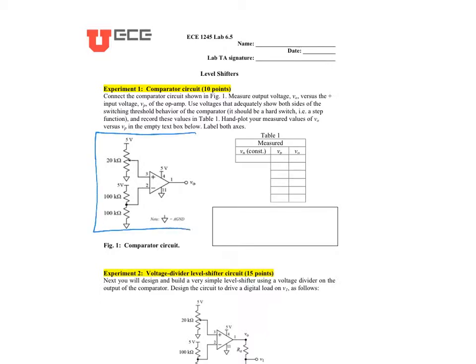If you take an analog block that is sensing something, and in this case we're using this pot as a sensor, then that analog block has some sort of analog logic that needs to drive a digital block. And if this analog block has a voltage range that is wider swinging than your digital block can handle, and in this case we're saying that our digital block can only handle 1.8 volts to 0 volts, so we need to figure out a way of taking this output from the analog block and distribute it properly when we're feeding it to the digital block.